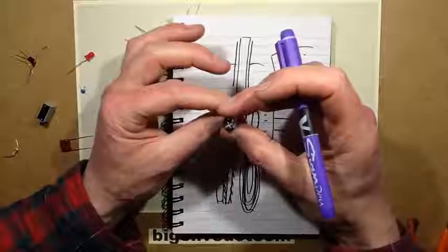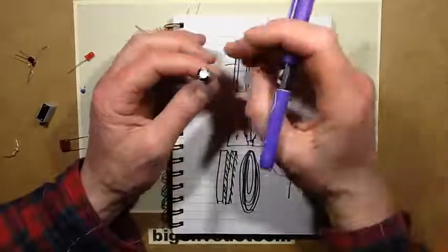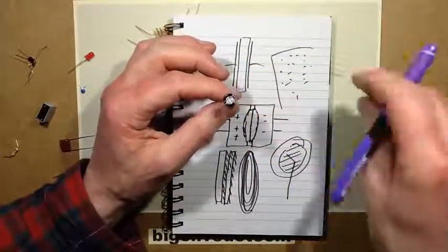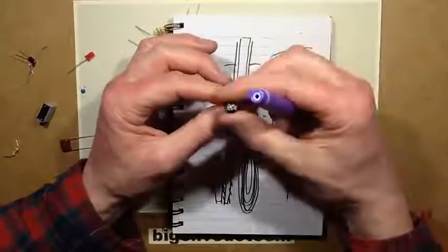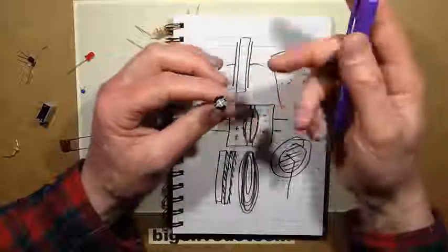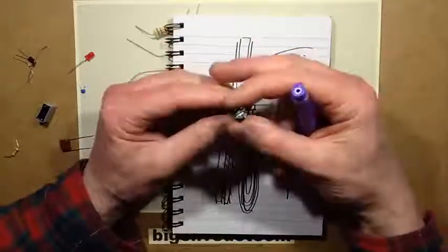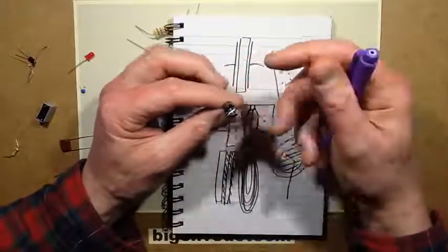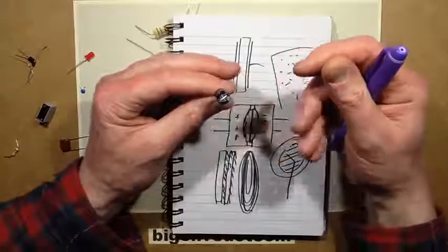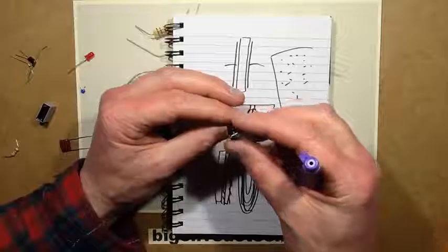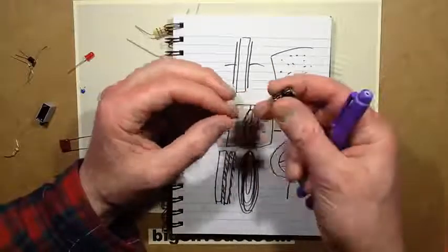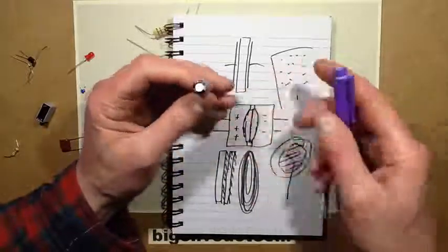Because traditionally, all the old video games from the 80s tend to suffer problems after a while with what's called drying out of the electrolytics. They still measure the correct capacitance, but their equivalent series resistance, the resistance to current flow through them, changes, it increases. And what that means is that they stop doing their job properly.